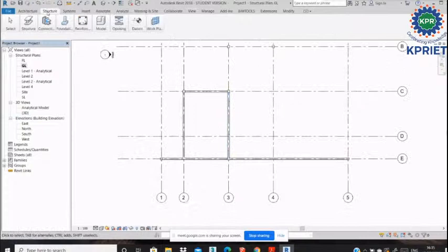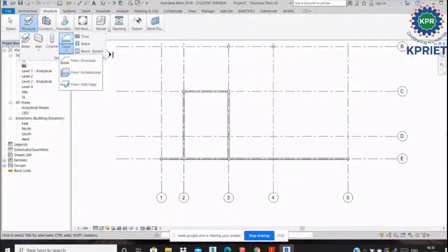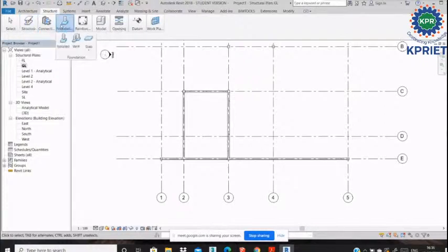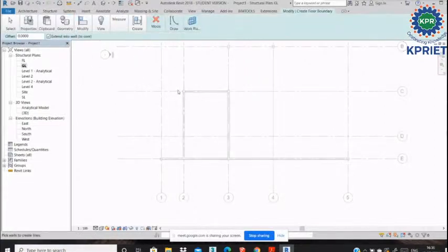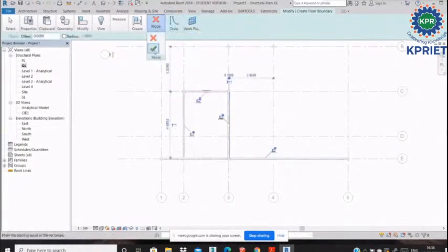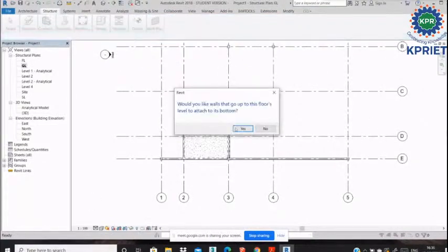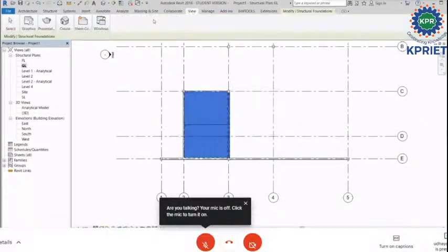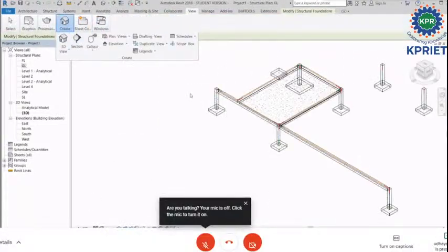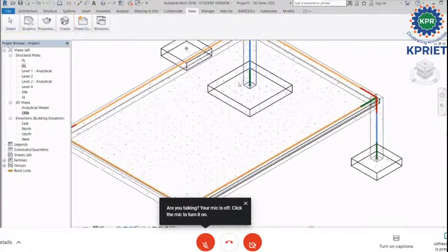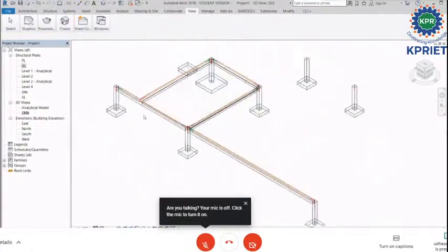Simply go to structural, right? This is a floor. You go to floor. Another way, you go to slab, is the foundation slab. The slab has some difficulties there, right? You go to structural slab. You go to draw. Then go to rectangular, right? Simply draw this slab. Then go to finish view. Go to create. Now let's see, automatically it will create a slab, right?